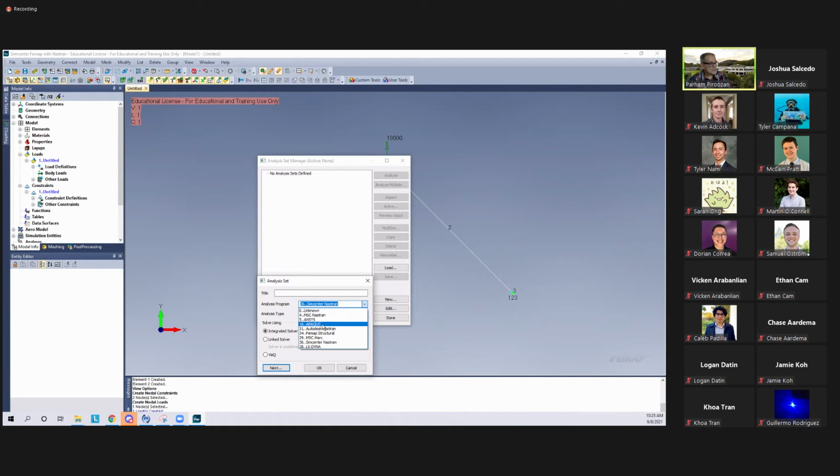If there is research, of course, we go with this one. And FEMAP structural, MSC, MARC, SimCenter. This is what we are actually using, so the program already selected this one for us. And analysis type, we can have different types of analysis. This is static analysis. If it is buckling, vibration problems, or a heat transfer problem, you can select, for example, this one, transient heat transfer or steady state heat transfer, and so forth. So it is a static analysis.